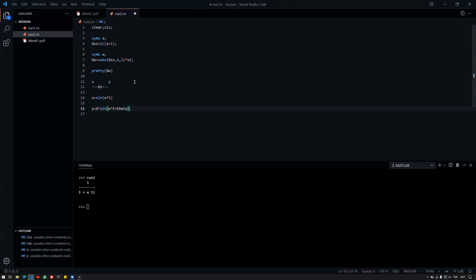Now, since we have something like this, it does not seem very helpful if we stay in the Cartesian coordinates. But if we change it into polar coordinates, we will see that the transfer function will have a certain gain and a certain phase. And how do we calculate this? Well, we take the real part, the imaginary part. So take the real part of g omega squared plus the imaginary part of g omega squared, and then the square root of this.